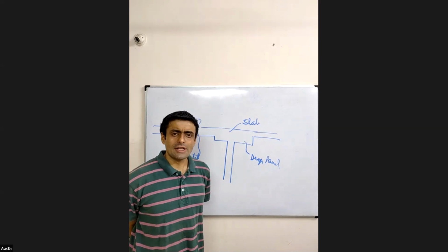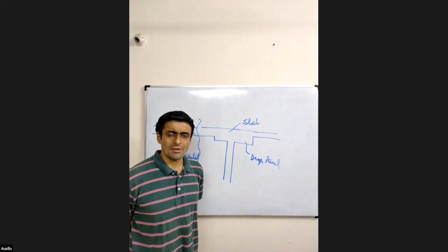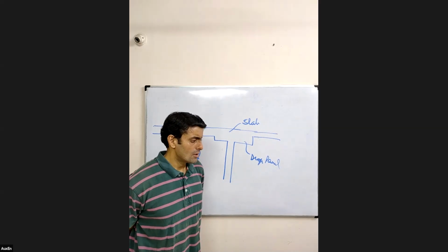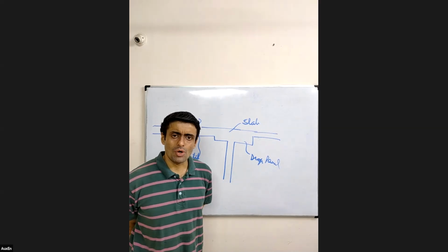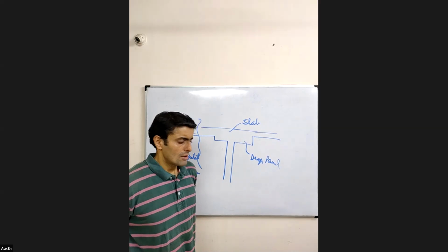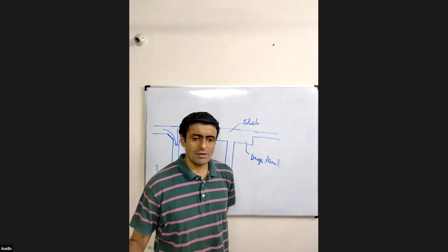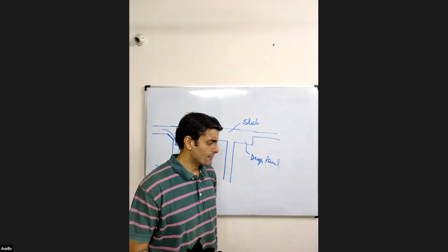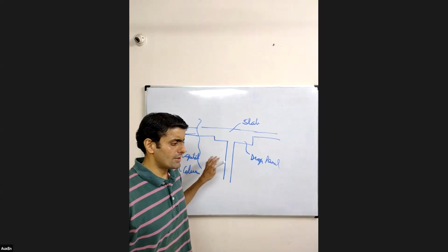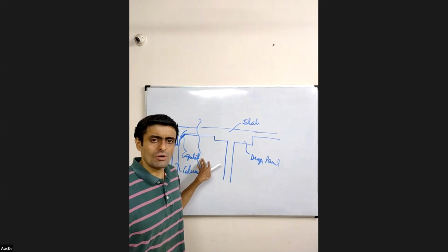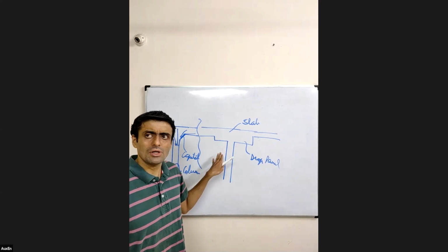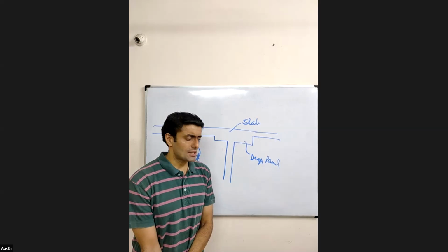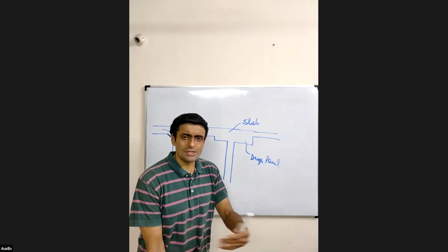So two broad strategies that you will see being used in flat slab. One is to go for column capital. One is to go for slab drops or drop panel. What can be another strategy? If let's say we do not want to go for capital also, we don't want to go for drops also, so what can be the second strategy, or I would say the third strategy?